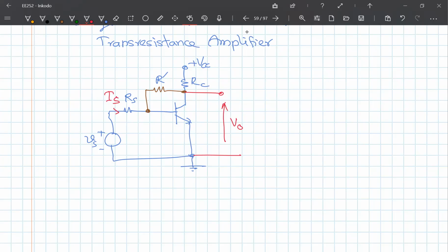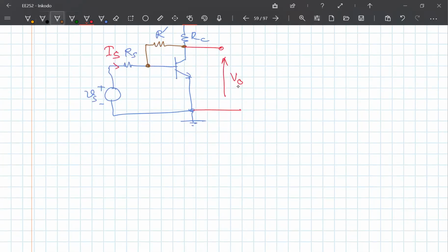So if you want to draw the equivalent circuit, or basically the circuit without feedback, you have to follow the same principles that we talked about earlier, right? What are the principles? In order to obtain the input circuit, set V out equal to 0 for voltage sampling, and set I out equal to 0 for current sampling. This is voltage sampling. Output is a voltage, so we sample using voltage sampling. So therefore, V out is made 0, so we have to short circuit this. As soon as you short circuit this, at the input you have this in parallel with that, right?